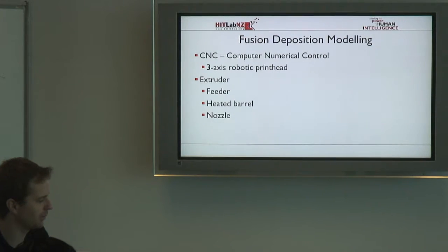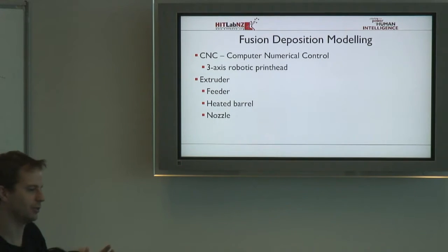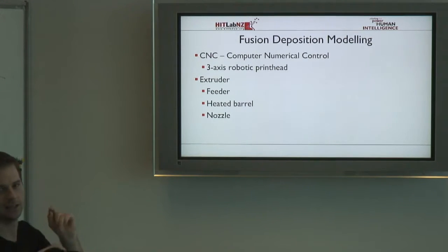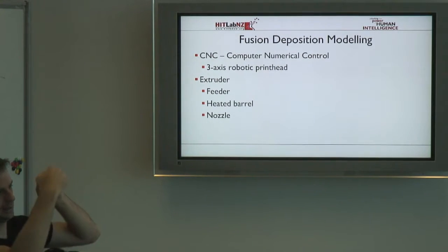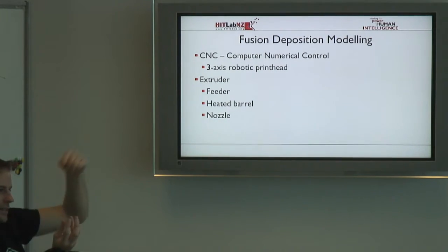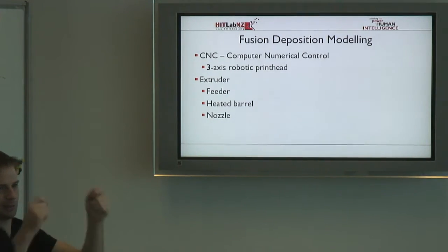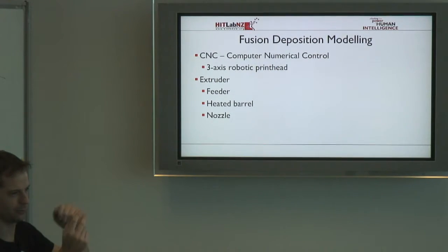There are different types of 3D printers as well. There are a few FDM machines which are known as Delta bots, which instead of having a box with 3 rods which go in different dimensions, are hard to describe. You basically have 3 pillars, and each one of them is connected via a flexible arm. So the print head is floating there, and it's got 3 things connecting it, and as you pull one of them, it will shift in that direction, pull the other one and it will shift that way. If you pull all 3, it'll move directly up. If you loosen all 3, it'll move down. And then if you pull and release the other ones, you can move it in all 3 dimensions.